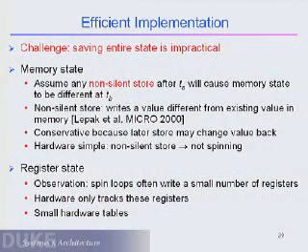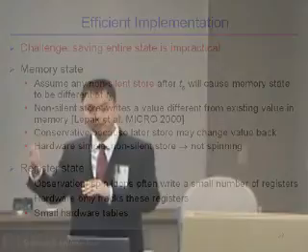Okay, so that just handles our memory state. Next we're going to jump onto register state. We make the observation that most spin loops are very small. So every iteration of the spin loop usually only writes to a small number of registers. Therefore, we don't have to checkpoint the entire register file in the CPU. Instead, our hardware can simply track the small number of registers in a potential spin loop. The resulting hardware then will only use very small hardware tables, so the cost is very low.